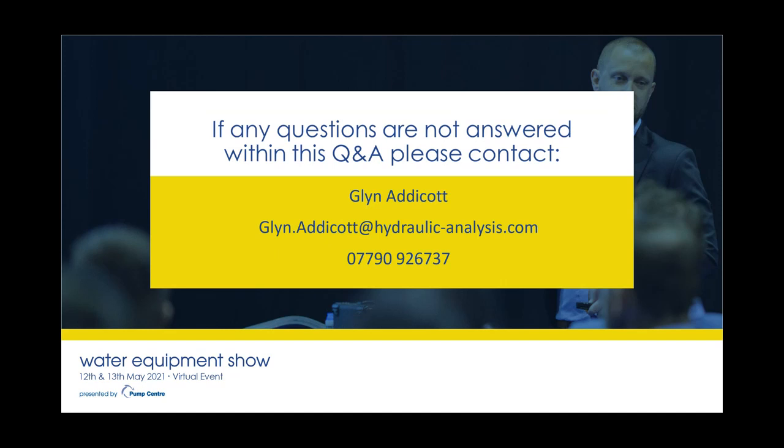For battery life with loggers, we can't have the loggers transmitting data every 10 seconds. What we tend to do is take readings every 10 or 15 seconds, but then they're batched in 30-minute intervals. So the logger will only communicate 48 times a day to the twin. It runs effectively half an hour behind real time, which is still very good. That really does save on logger life, and we can get many years out of loggers with that approach.